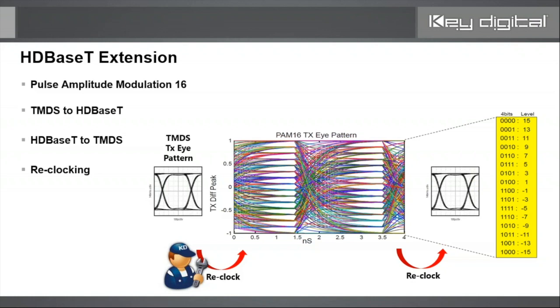And those boxes were so lousy, the output signal, that when you stretched it with HDBaseT, the resultant image was so bad that by stretching it at the receive side, that reclocking, the display could no longer tell what was a 1 and what was a 0. You just had a black image. And this was known in the industry as the HDBaseT clock stretching problem.